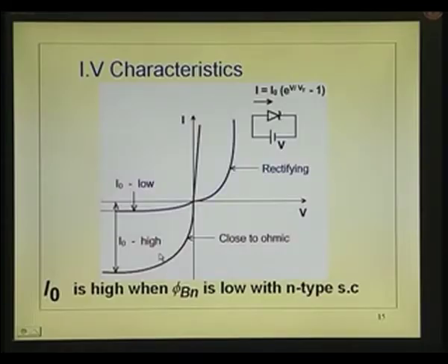This is the key thing what we have started. So, if you take a look at the equation of that metal semiconductor contact, I have drawn two characteristics, metal and N type semiconductor, and I have marked here the diode and the IV polarity, I is in that direction. So, this is the I naught e to the power V by Vt minus 1, and this is I naught.